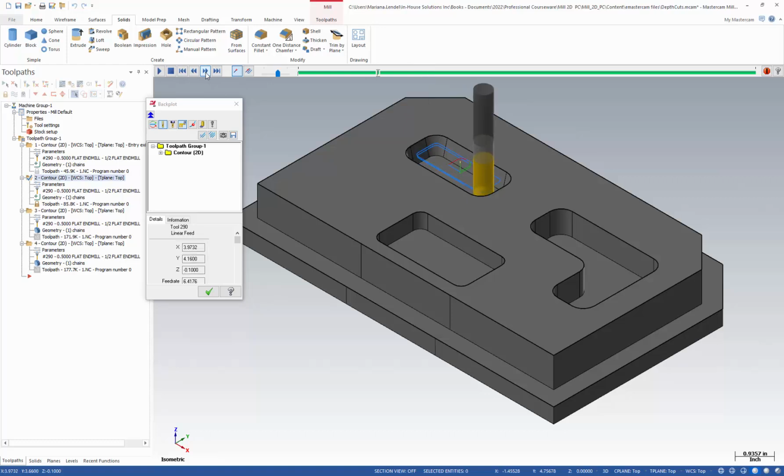So the tool moves in Z and also in X and Y. Again, another depth of cut and then moving along the X and Y plane like this. It's not going to be a great finish on the walls right now. The roughing step should be smaller than what I chose, but this is one way in which you can machine pockets with taper walls.